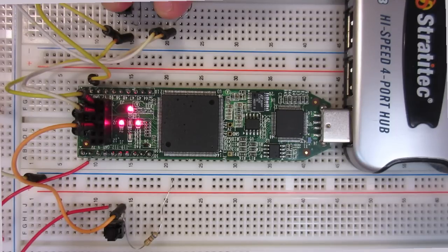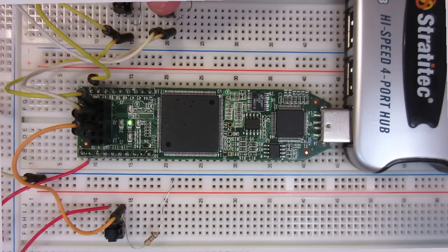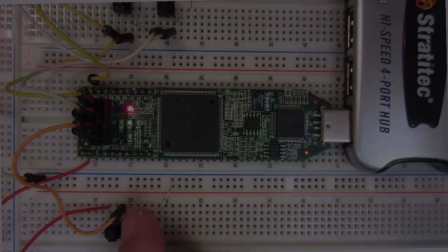That's the carry latch. That's the latch part that remembers that a carry happened. So even after I take my fingers off, that LED stays lit now, and it'll stay lit until I go over and hit the reset button near the bottom of the board. There it is, it went off. So that pretty much works the way we expect. 1 plus 0 is 1. 0 plus 1 is 1. Both of them come on. That's a 0 with a carry, and the carry's latched. It all works.